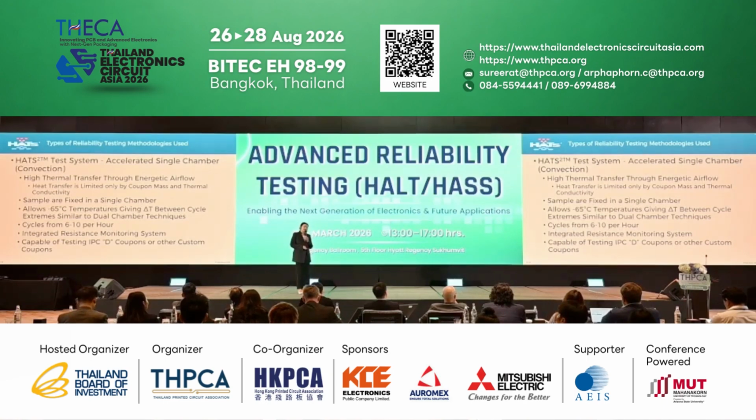It allows the airflow of the lowest testing condition to be -65. The high temperature can go as high as 265 degrees C. It can shorten the test cycles from typically, a traditional thermocycling test is 1 cycle per hour. With HATS2 testing, it can be shortened to 2 to 10 cycles per hour.